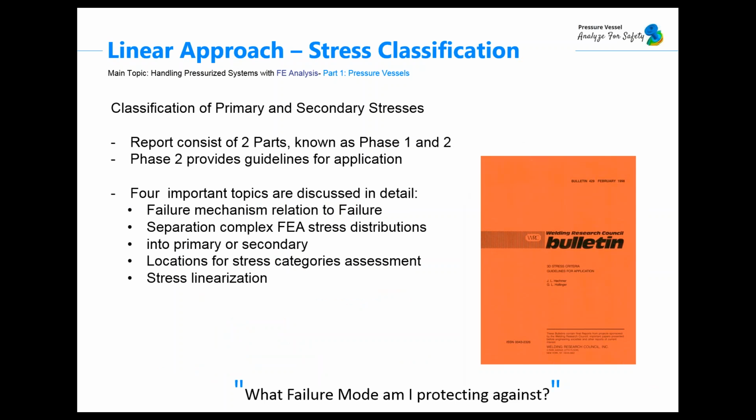So this type of questions are very important, and usually FEA pressure vessel designers are facing them all the time. There have been a number of discussions of this topic. You can find a lot of information on the forums. But the object of the whole exercise, I mean the object of the stress linearization, is not to find a linear profile of the stress, but actually to sort the statistically determinate stress components from the indeterminate components and peak stresses.